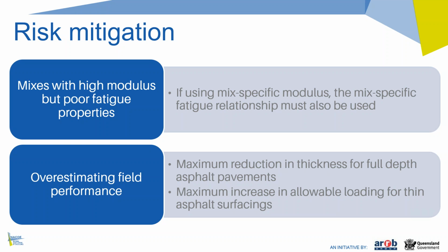So on that basis, the technical note includes limits on both the allowable reduction in thickness that can be gained in full depth asphalt pavements using the mix-specific modulus and fatigue relationships. That reduction is currently set at 10%, but we're open to, I guess, discussion about that value.